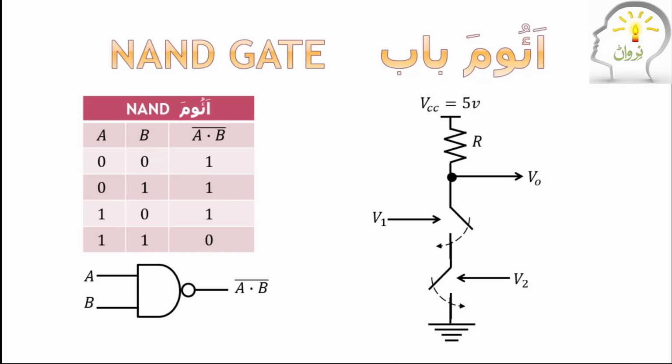If any of the switches is open, resistance here will be how much? Infinite. By the voltage divider rule, what will the output be? 5 volts. Maximum. Write 5 volts here and 5 volts above. Okay, yes, logic.